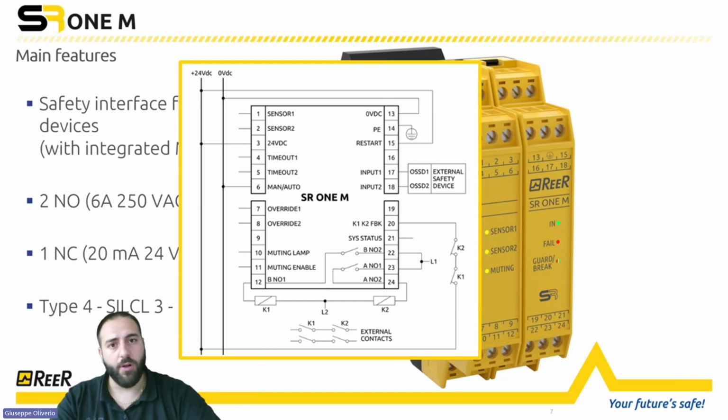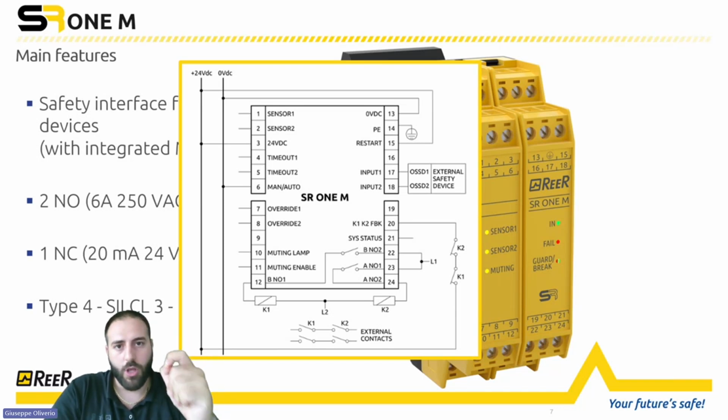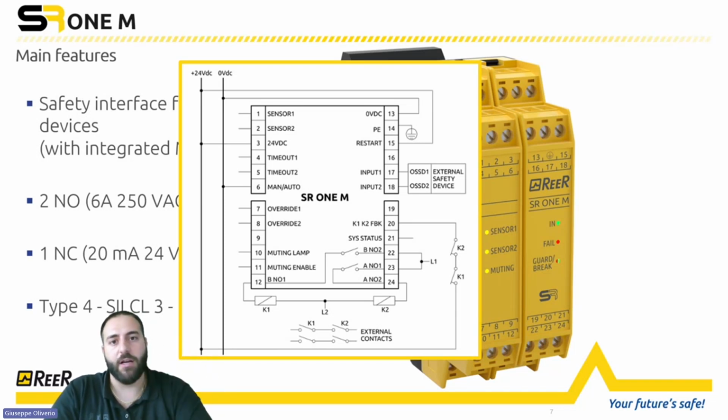The muting enable, we will see the information about the muting enable during the webinar dedicated to the SafeGate, that is our safety light curtains with muting integrated function. But what is important is that in order to consider sensor 1 and sensor 2, you need to wire an external sensor, an external signal to muting enable in order to enable the muting.